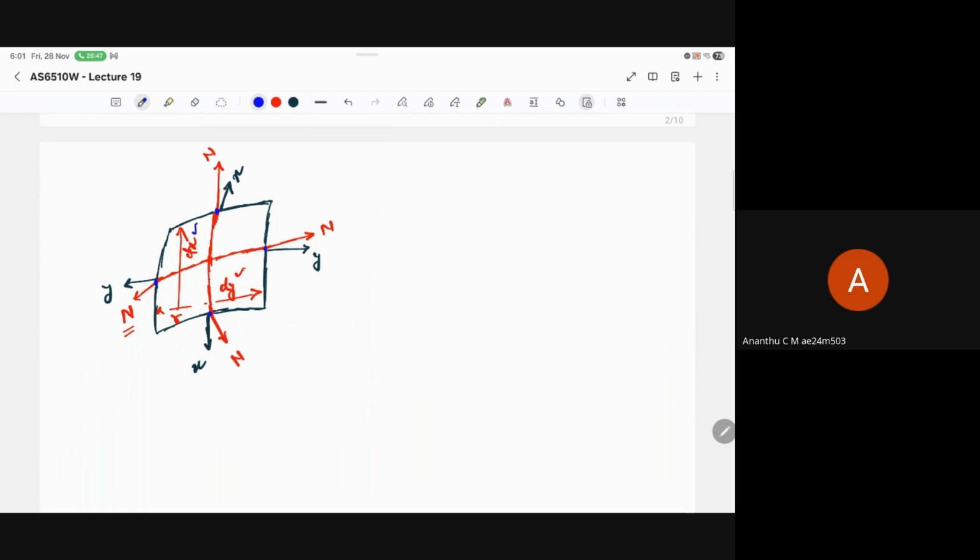Now, this is the deflected element, which is coming from the deflected shape of the membrane. That means if you talk about the angle here, this is the deflected shape. So at this particular point, this is the slope with respect to the x-axis. This is the slope of the deflected shape, and to define that, this is basically your ∂w/∂x. Okay.